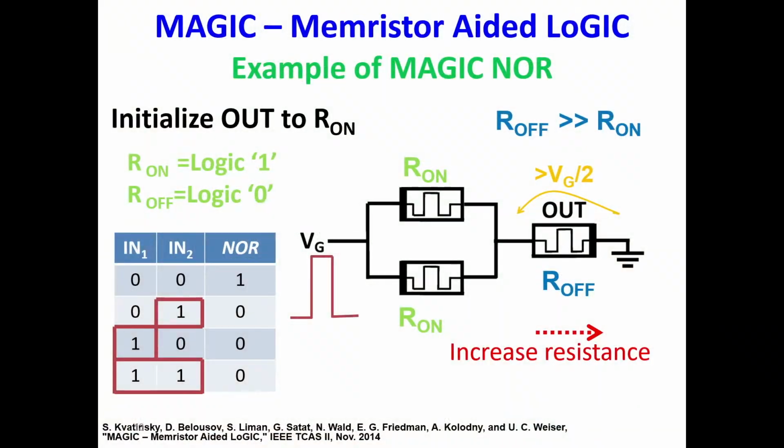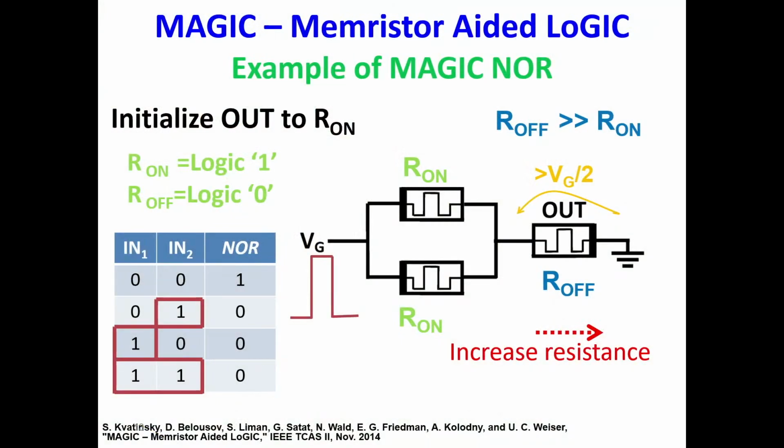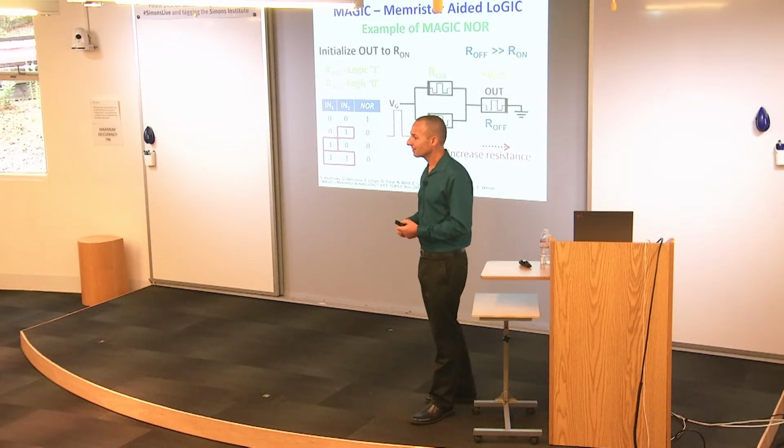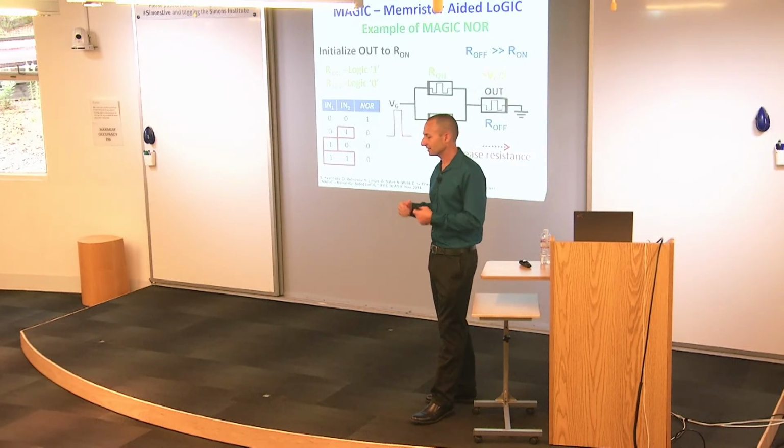Do you know how much charge is required to flip a memristor compared to a CMOS gate? Is it much more? It's much more energy that's required, yes. That's true. If you compare a CMOS gate to a stateful logic gate, in terms of energy, the energy for a CMOS gate is much lower. But since we will do it in the memory, we eliminate the need to move the data, which, as Mark and Dave Peterson talked about, is most of the energy, and not the switching of a gate. Because you had to drive a line to get it to memory anyway. Exactly. That's where we get the benefits, not from the single gate. If you compare one gate to the other gate, definitely CMOS wins.